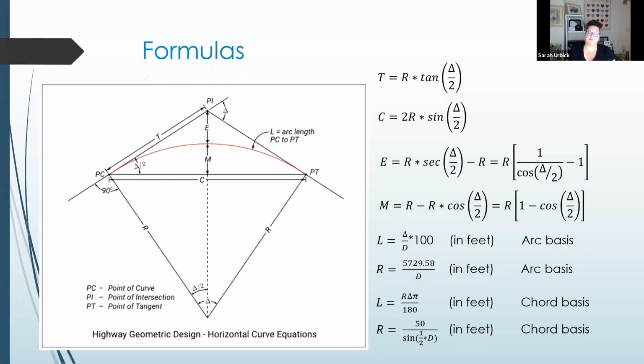We can find out what that information is that we need, right? The length times the angle divided by 100 will also give us that interior angle. So that's how we would solve for those interior angles, the deltas, to come up with our chord length and finish filling out that table, right?